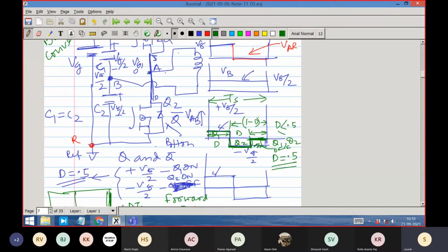But sometimes things are not so ideal. So depending upon the resistance or impedance, this voltage may drift because you are not solidly holding it. Solidly holding is holding it by switching. So if both Q1 and Q2 are off, then the node A will be kind of floating.